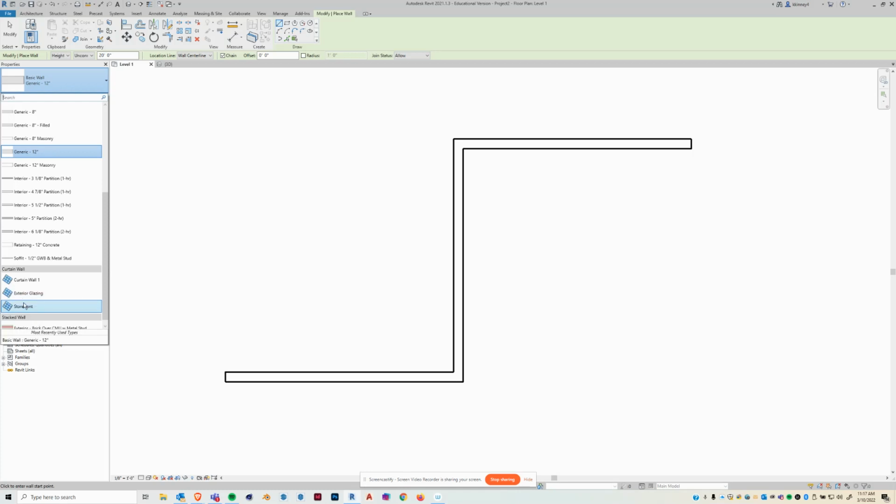And the last one is a pane of glass with divisions with mullions applied to all those divisions. We can easily turn this one into this one, and vice versa. We can turn off the mullions in this one, and we can delete some of the grid lines and take it back to this one.